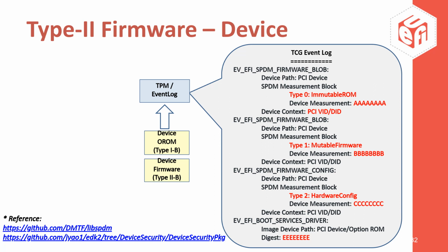And the second is a device security package, which uses this libSPDM to communicate with the device in the EDK2 environment. So an EDK2 driver can use SPDM to talk to the device which implements the SPDM protocol and retrieve the device SPDM measurement from the device.